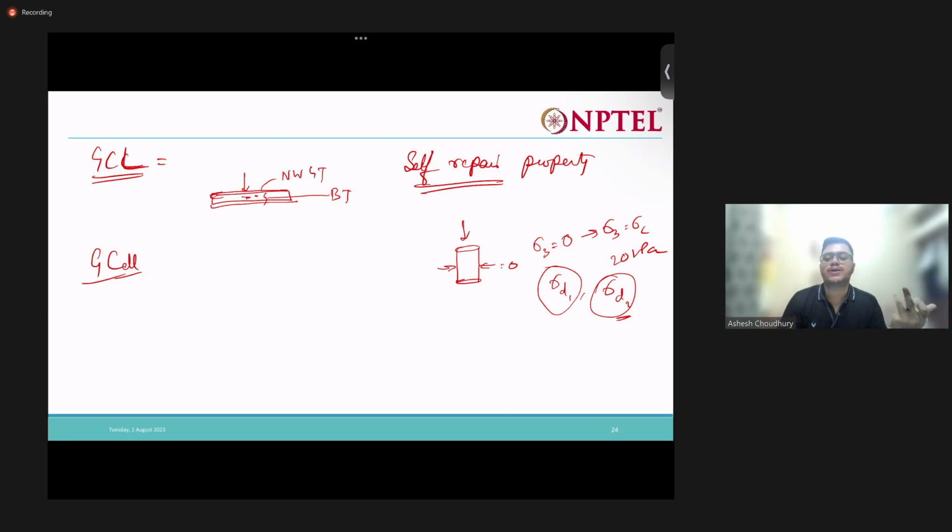So this is the same property with which the geocell works. This is a confinement product. It confines the soil, and this confining pressure acting on the soil is strengthening the soil. That's all. So where are these geocells used? These are also used as erosion control devices. These are used to protect steep slopes, and to build retaining walls, reinforced earth walls. Also as sub-base support such as road bases, and railway tracks. All these things, these are used.